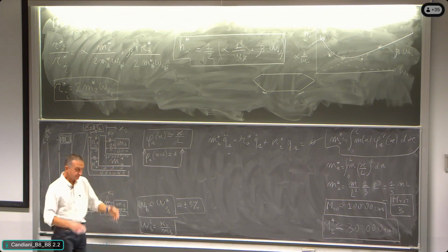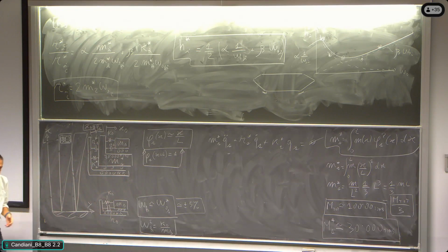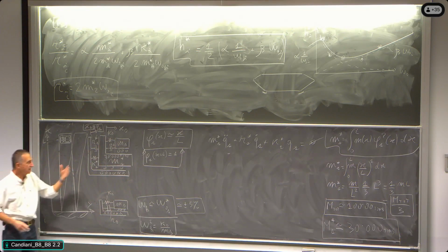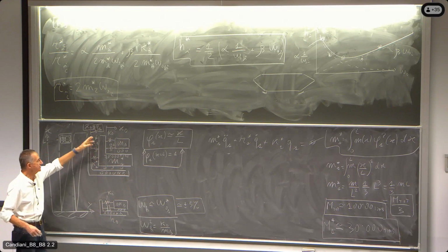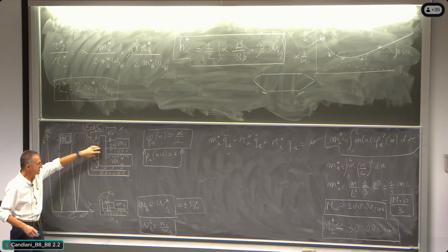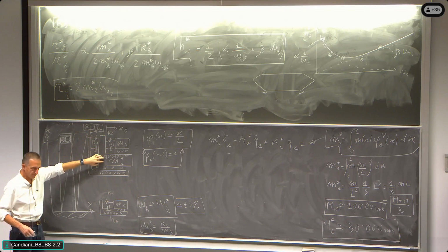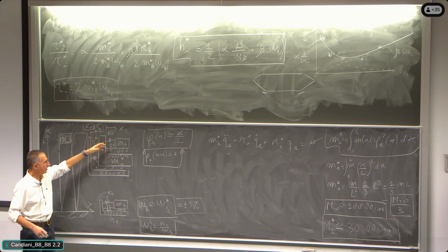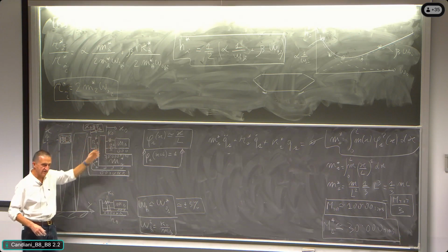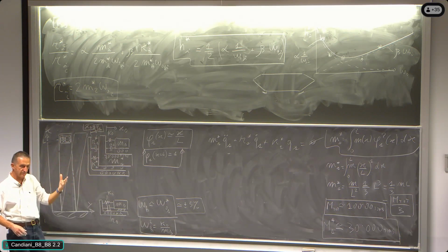All right, this equation shows that the system is a 2-degree of freedom system where there is a coordinate that is x1, that is the motion of the top of the building, that is q1, and a coordinate that is x damper, that is the relative motion of the damper with respect to the building.